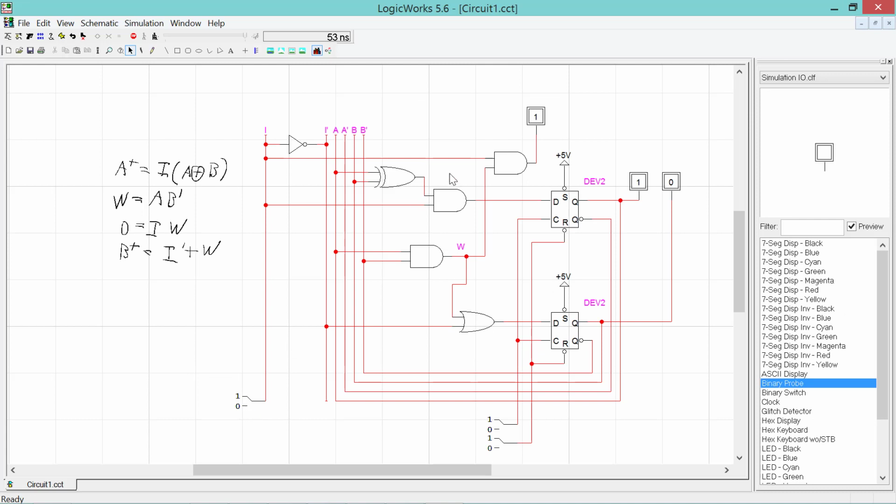Well, check the input and check this output pin. If we change the input pin, clicking from 0 to 1, the output pin changes immediately. Is this expected behavior for a sequential state machine? Well, it seems counterintuitive, but because this is combinational logic and it is directly affected by the input pin, it is entirely conceivable that it will affect the output pin immediately.